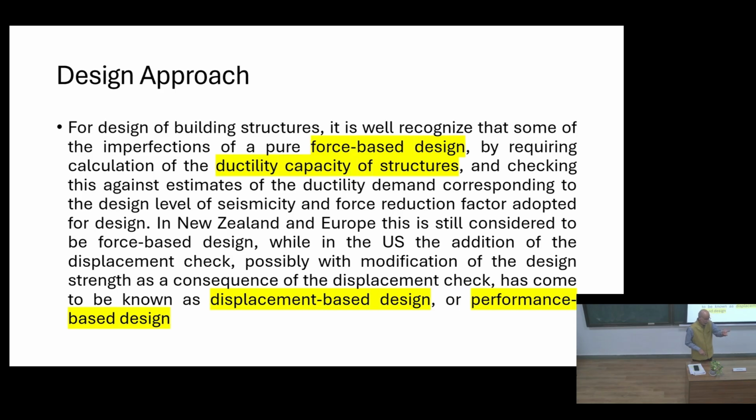The limits you fix in the design are serviceability requirements, where you have a displacement and a crack pattern, because if cracking takes place, the stiffness goes down. So they started moving slightly away from this concept toward displacement. So now you have a force-based design and you have a displacement-based design. There is a difference in the approaches there.